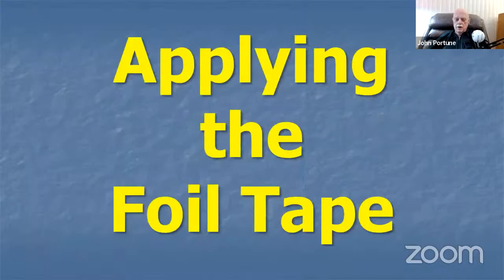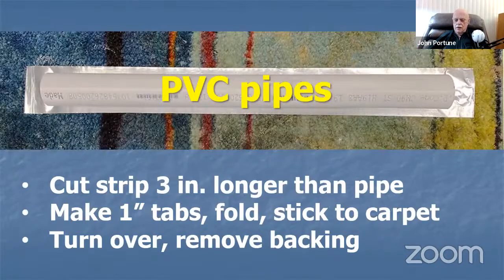All right, putting the tape on. This is a little difficult. I'll go through it quickly. You cut a strip that's 3 inches longer than the pipe, lay it down on a piece of carpet, fold the ends over, pull the little tab of the foil backing off the foil, and stick it to the carpet so it's nice and flat. Then pull the backing off so that the sticky surface is looking right up at you. And then push the pipe carefully, very carefully, right down in the middle of the tape.